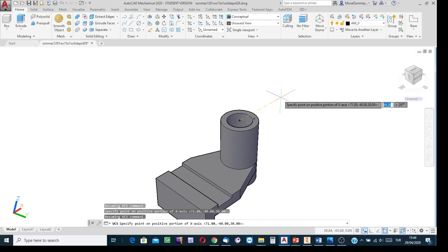Well, that is the origin. Say the abscissa value for the point through which the abscissa axis passes is half of the circle's diameter, 32 divided by 2, that is 16. Write such a number. Click the comma key. Ordinate value 0 for that point, because the point is along the x-axis. So ordinate is 0. Press enter.